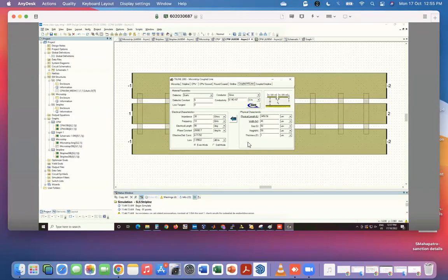But there are situations where slot lines are actually used. Remember, if we were trying to calculate the impedances, we saw that we were not able to get a 50 ohm slot line. So it has a different range of impedances which are easy to realize. In some cases, you make resonance structures which are part of an overall circuit, using a slot line like that. That is important for creating the overall response.